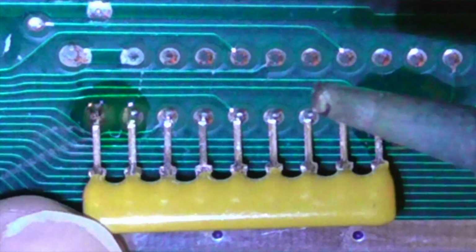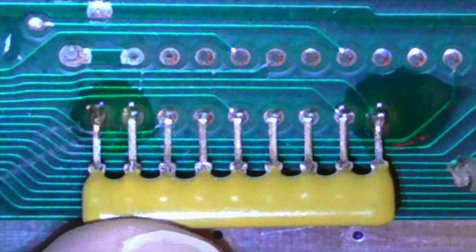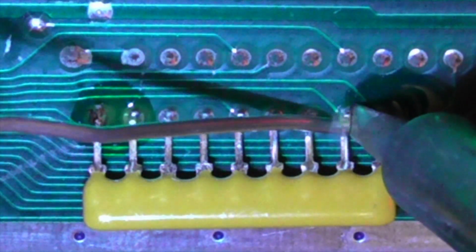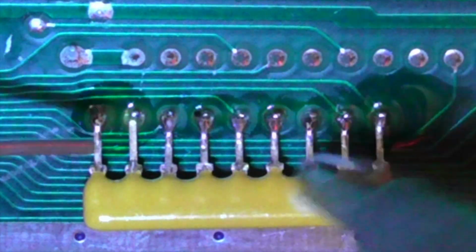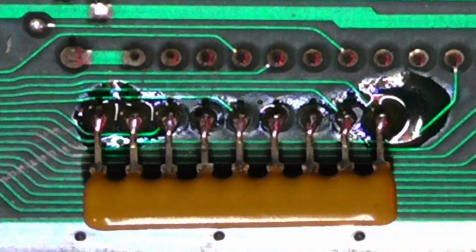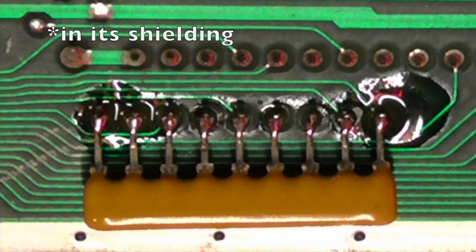So I'm pushing this in as much as I can so that as many of these pins touch the other solder joints, which should then make it easier for me to go along and join them up. Which is what I'll now try and do without desoldering the ones next to them. I know this isn't going to be the prettiest job in the world. I just hope it's going to be strong enough without interfering with the operation of the board, or how far it sits in its case.